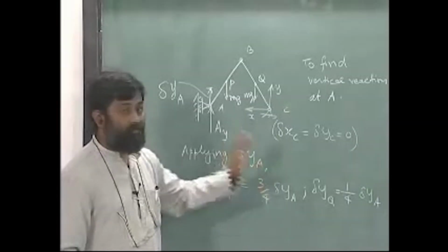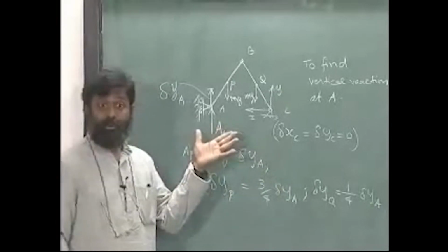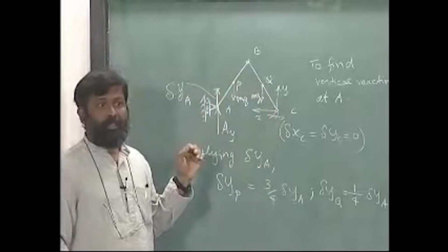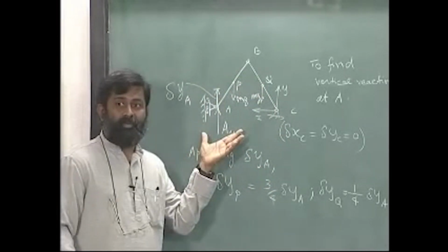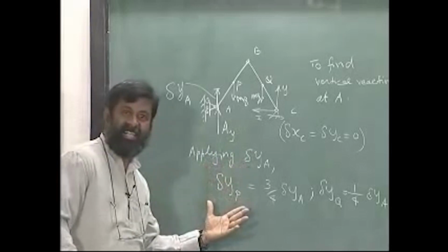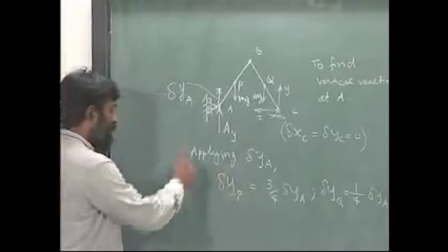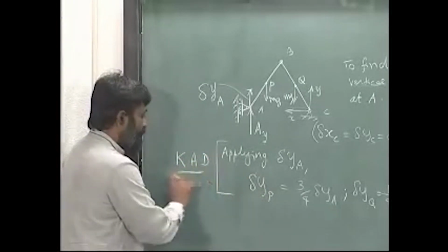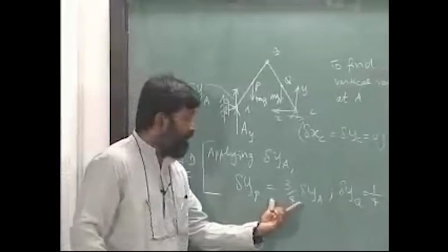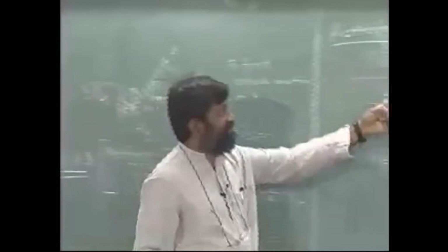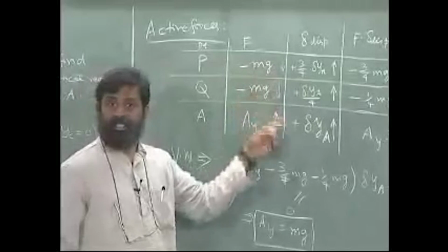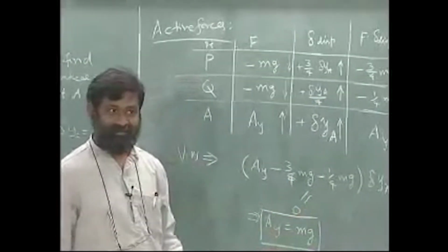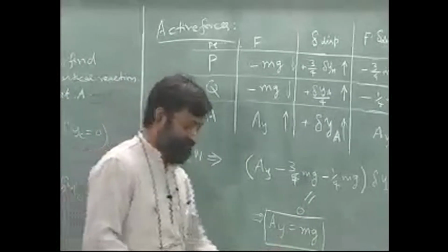Okay. The advantage of this is you do not have to do the entire equilibrium for this system, but then you have to sacrifice on finding out kinematically admissible displacements, kinematically admissible displacement, and this is crucial. Okay. And mind you, the signs are very important to get the appropriate equations, right.